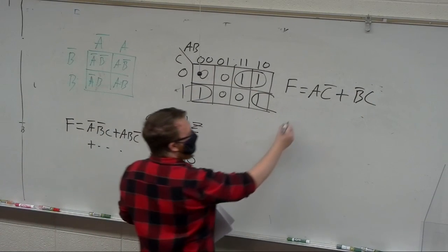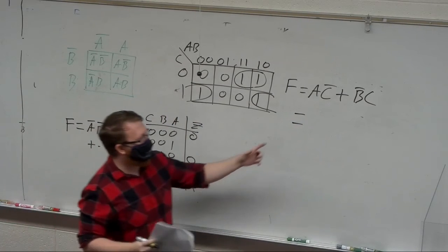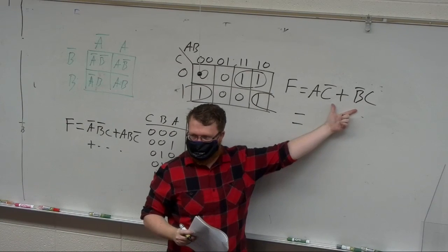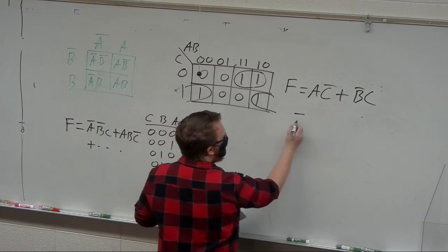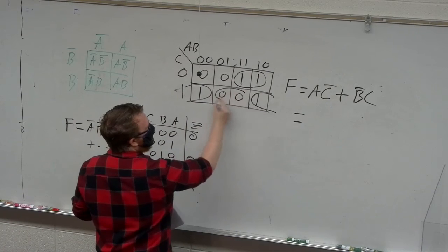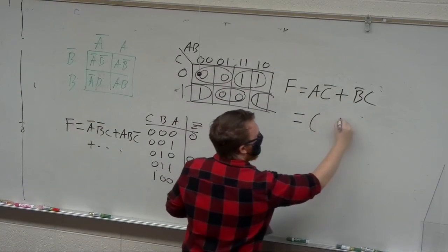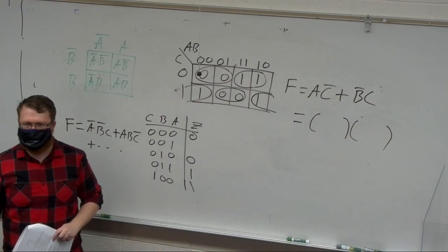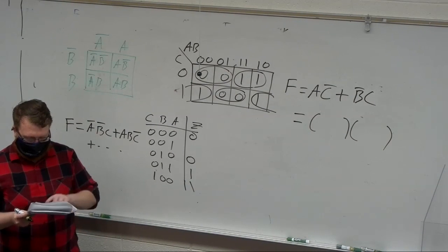For min terms, you can generate this, and remember, this is tying back into the propagation delay, where now I also have a minimized propagation delay because of the form of the expression. We can also start circling the zeros, and I'm not going to go through that right now, but it would end up being a sum of products instead of a product of sums. It switches around. We'll get into that probably next time specifically.